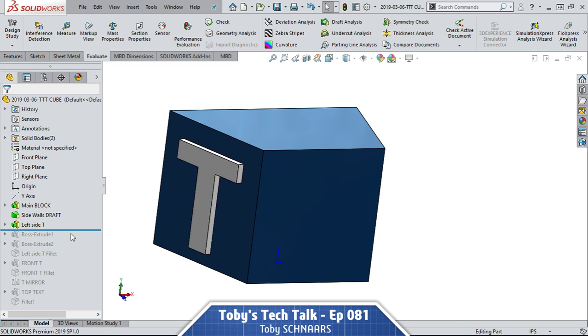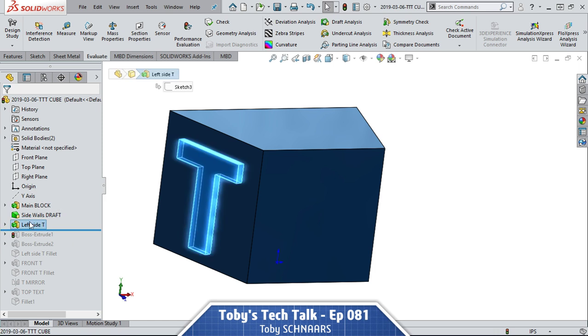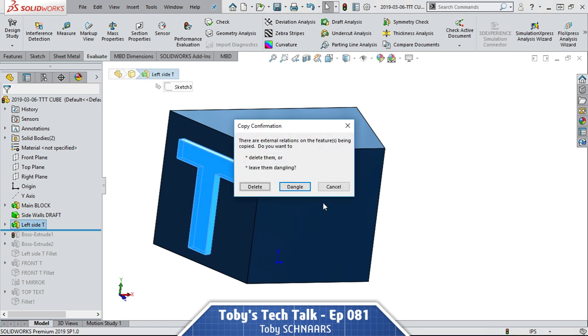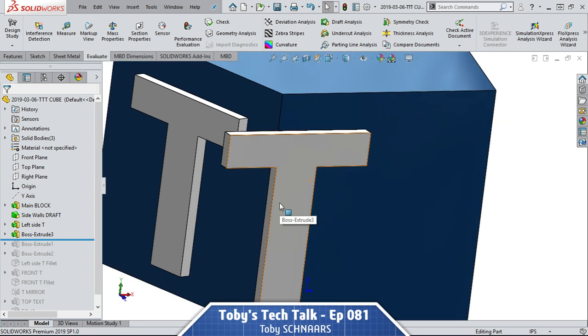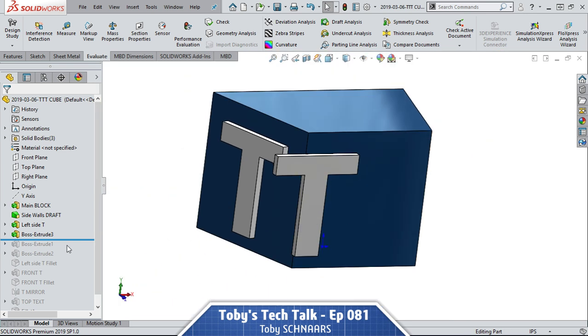So I can hold Control and drag a feature from the SolidWorks tree onto my SolidWorks model, and I can actually make a copy of that feature by doing a Control drag. So Control C, Control V, or Control drag to make a copy of your features, another really, really good shortcut to remember. That also works great in assemblies.